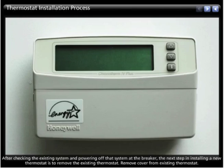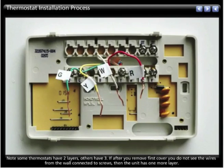Thermostat installation process. After checking the existing system and powering off that system at the breaker, the next step to installing a new thermostat is to remove the existing thermostat. Remove the cover from the existing thermostat. Now, you'll want to note that some thermostats have 2 layers and others have 3. If after you remove the first cover, you do not see the wires from the wall connected to screws, then the unit has one more layer.